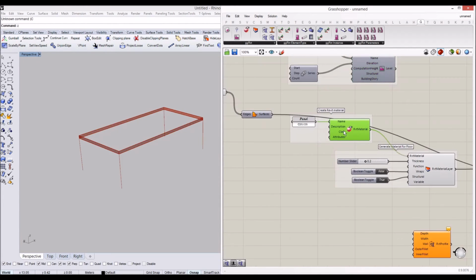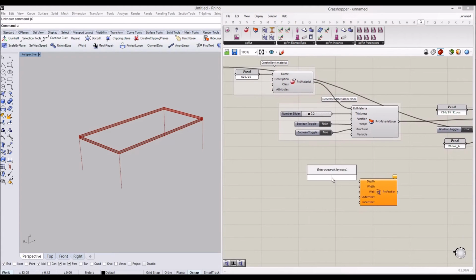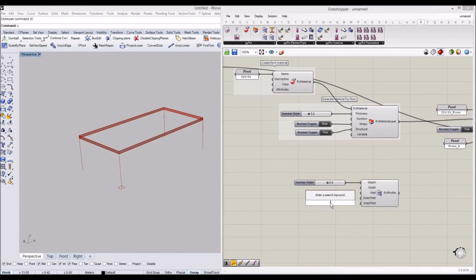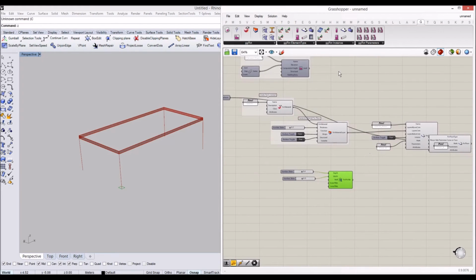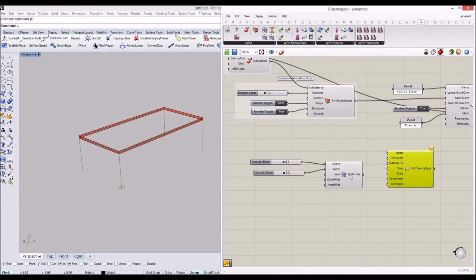So now I'm going to create depth and width for our concrete beam, which will be 0.4 meter of depth, and then we'll make 0.3 meter, 30 centimeter, yeah, for the width of the beam. So that profile is here, we can apply, and I'm going to create our beam parameter component in GeometryGym.